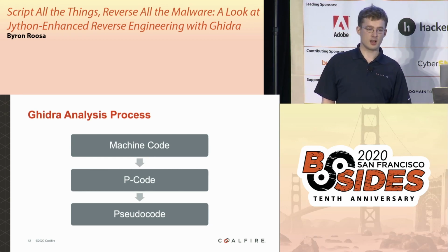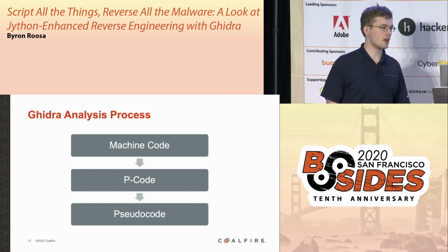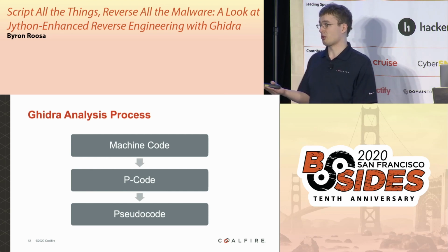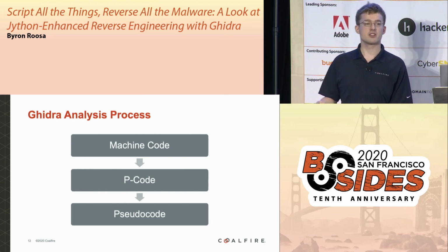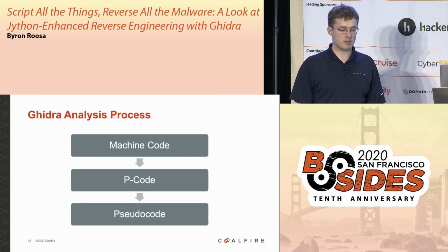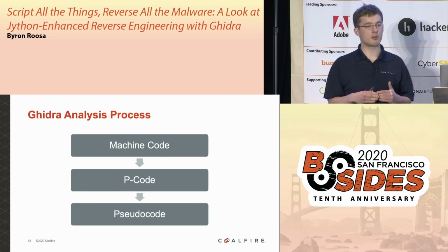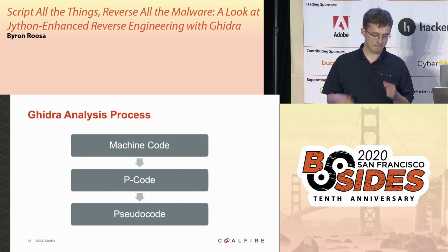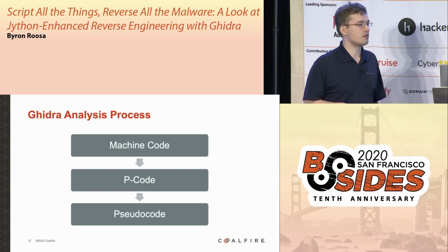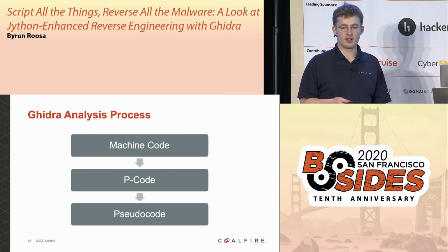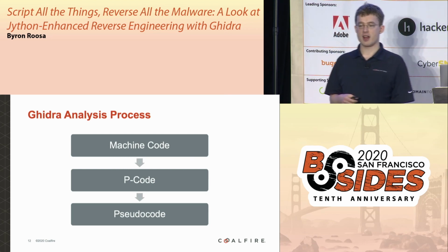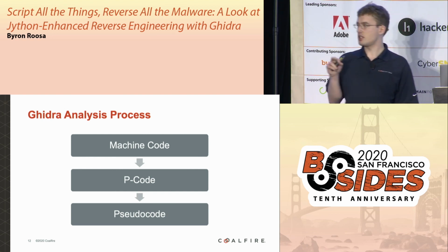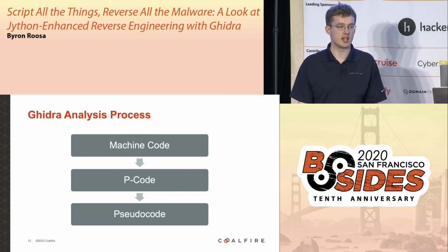This is an architecture-agnostic language, kind of akin to what a compiler would use, for those of you who work with compiler internals. It's really a register transfer language. And basically, this allows us to totally separate the CPU architecture from what's happening within the actual CPU state. This is part of the reason why we have 15 different architectures, because we can just add a new architecture by creating a configuration file that defines how each CPU instruction changes the CPU state.